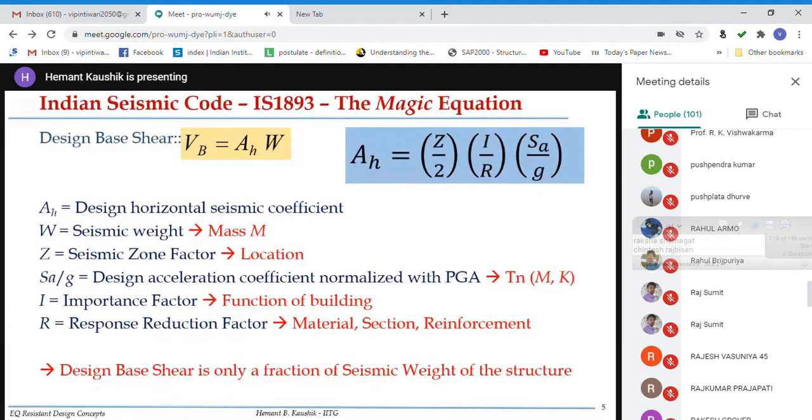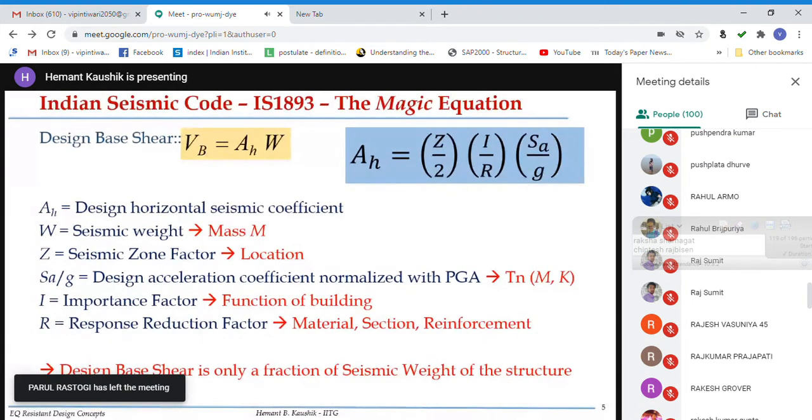Okay. So what is this 2 doing there? The role of 2 is very interesting. Now, if you want to design your structures for a low level of shaking, of course, the shaking is governed by the seismic zone factor, zone 2, 3, 4, 5. But for some important structures like bridges, you can design the bridge for a functional level. Functional level in the sense that for regular small earthquakes which are of magnitude 6, 5.5, 6.5, or you have to design these bridges for a very high level of earthquake shaking, let us say 8.5, right?